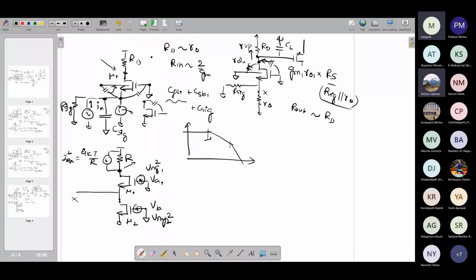All right. So I have the input, the small signal current provided by the M2 is simply GM2 square into VNG2 square. And then this small signal current directly flows into the resistance, because this is a cascode device. Whatever small signal current flows into the source, the same comes out of the drain, and therefore it goes into the R. So this into R square is going to the voltage because of this one. What is the output voltage because of the M1?